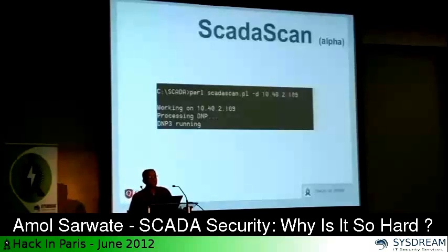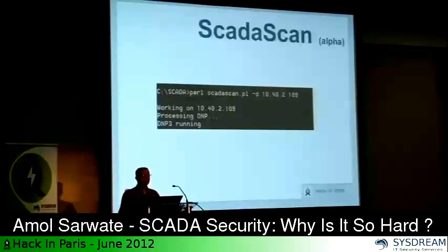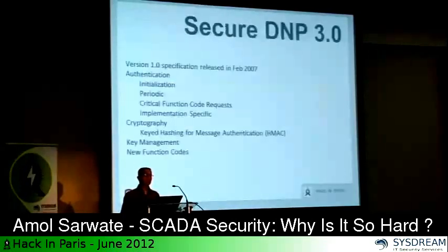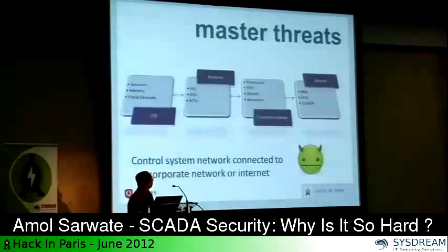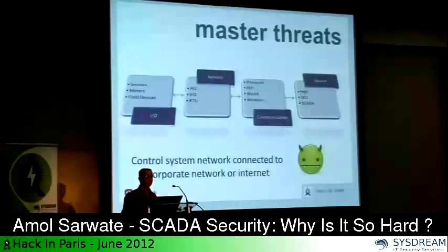But again, all is not lost. It's not all doom and gloom. What DNP3 did was in 2007, they came up with a newer specification of this protocol, which has many of the functions that you said it has, hashing and cryptography and a lot of these things that newer protocols support. So if you use Secure DNP3, which is a newer version of that protocol, I think you are pretty much in good hands.